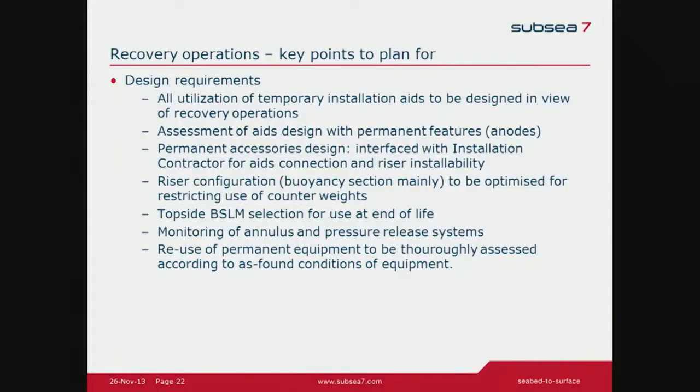Assessment of head design with permanent features. If we need to have some installation heads installed that need to be used again for the recovery, then we need to include some anodes, for example, to have them ready for recovery many years after. Permanent accessories design: interface with the installation contractor for head connection and riser instability. That is always what we find out at the end of the projects.